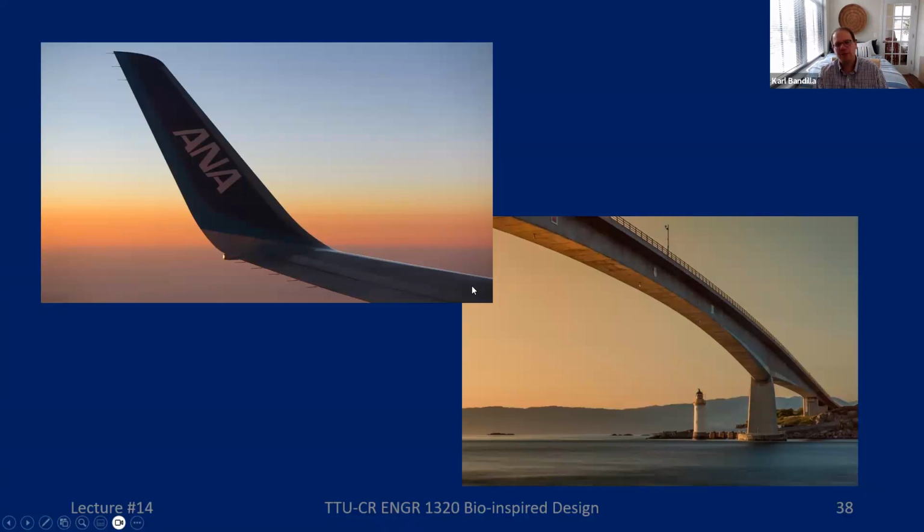But we've learned, right? So we can make differences. We can actually use nice curves, right? So this is the wingtip of a plane. This is one of those things that engineers stumbled onto, right? So until 20 years ago, the wingtips were just flat, right? There was nothing on this. Basically, as if I cut along this line right here, this blue line. But it turns out that if you add this little vertical or almost vertical wingtip, you actually get a lot less drag than if there's nothing there.